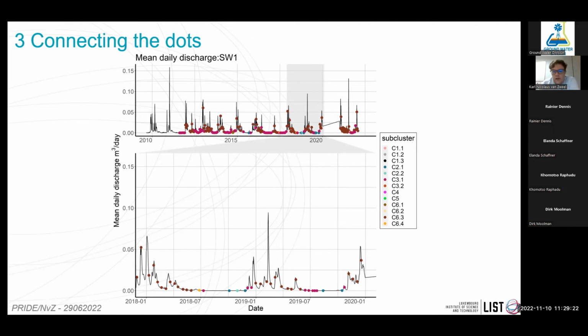If you have dry conditions and a small rainfall event, the first peak is usually just water that is stored in the riparian zone that was chemically altered a bit. It gets pushed into the stream, and then you see some of the deeper flow lines when it is really dry. Just to give you a bit of background, in our catchment the stream almost dries out completely in summer. This is due to the fact that evapotranspiration plays a large role in the water dynamics of the system. So you can almost have a completely dry system in summer where there's almost no water, and then in winter it fills up again.